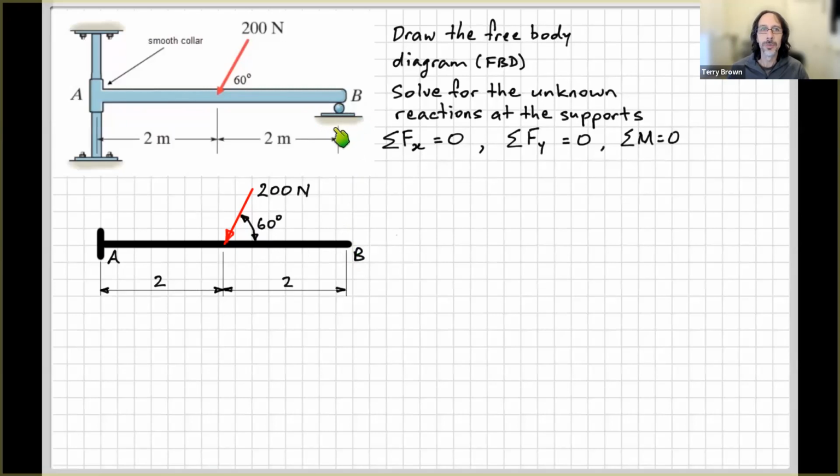So that should be fairly easy for you by now if you've done some work on rigid body equilibrium problems before. We know this is a roller support. The component can move horizontally freely, so no support reaction force in the horizontal direction, but it does constrain the component AB from moving in a rigid body way up and down vertically.